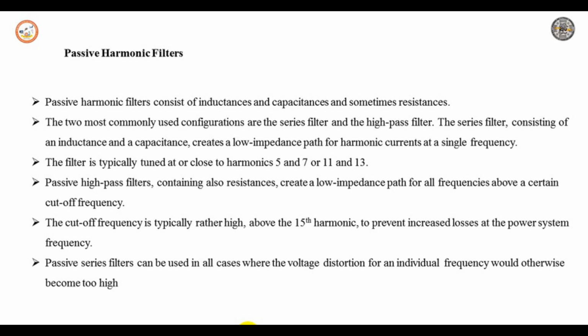The same algorithm for mitigating the voltage fluctuation and harmonic distortion can also be implemented in a series converter. An interesting application being discussed in the literature is to implement it at selected frequencies. At these frequencies, the converter behaves like a resistance, providing damping in case of harmonic resonance. Such an approach would be relatively simple to implement because no additional hardware is needed. The requirements on the accuracy of the algorithm, like the frequency tuning, do not have to be high because the damping is provided by many individual customers.